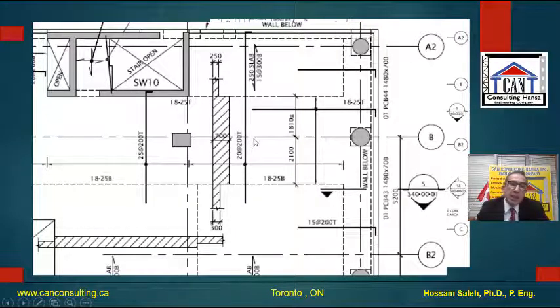So it shows you there is some flexibility in the designation of your reinforcing bars. You can have the spacing, so number 20 is a diameter at 200 millimeter top, or you can have the number of bars and the diameter top within a specific distance or range.